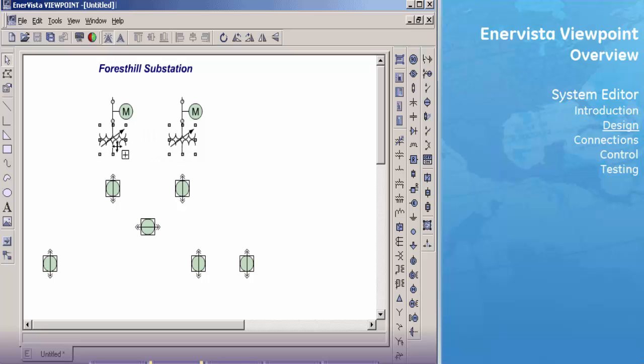Let's add some lines to connect the system of breakers together. Lines, like any other schema component, can be copied and moved around easily to finish up drawing the schema quicker. Once all the lines have been dropped on the screen, the schema will look like this. Additional elements such as arrows can be added as necessary. In this case, we add the arrows to follow electrical guidelines.